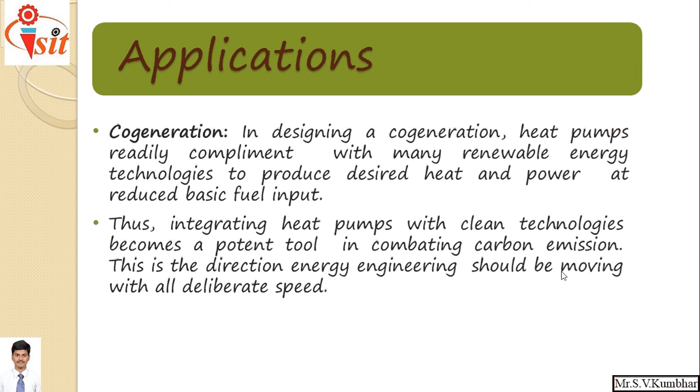Next application, cogeneration. In designing a cogeneration system, heat pumps readily complement many renewable energy technologies to produce the desired heat and power at reduced basic fuel input. Therefore, integrating heat pumps with clean technology becomes a potent tool in combating carbon emission. This is the direction energy engineering should be moving in with all deliberate speed. The heat pump can be easily combined with clean sources, that is wind energy and PV cells.